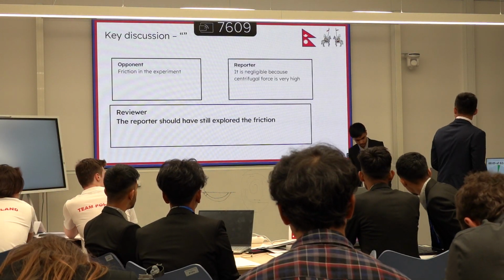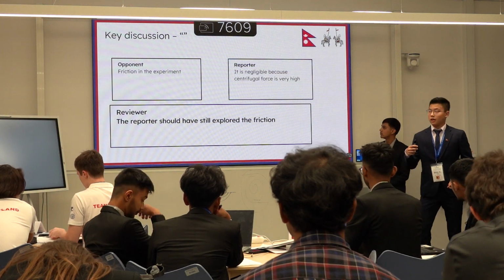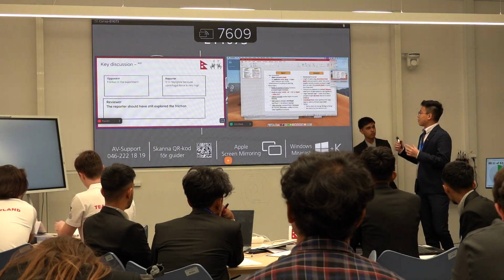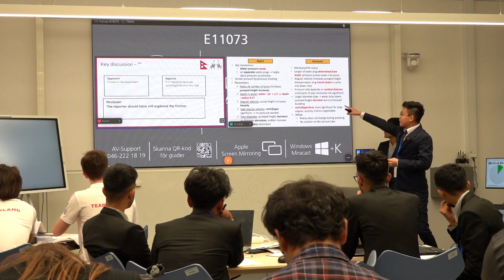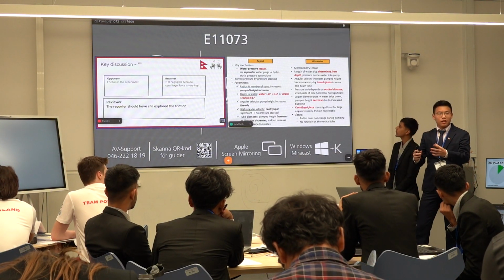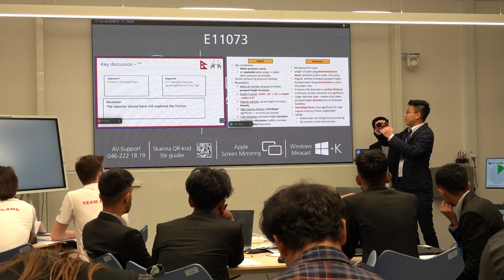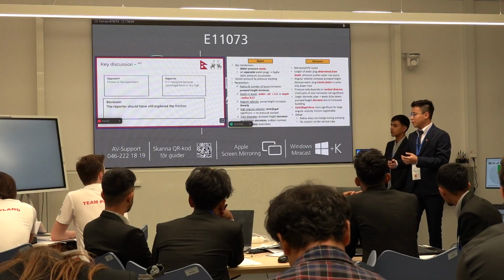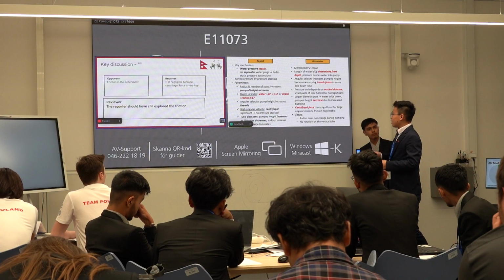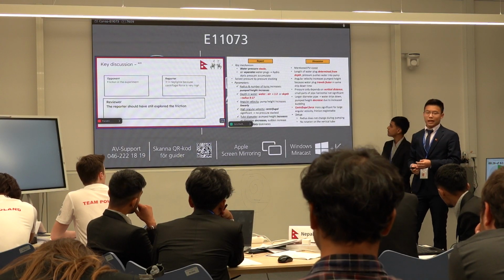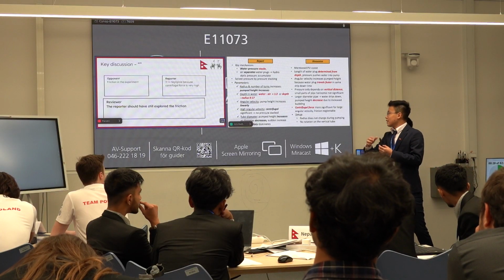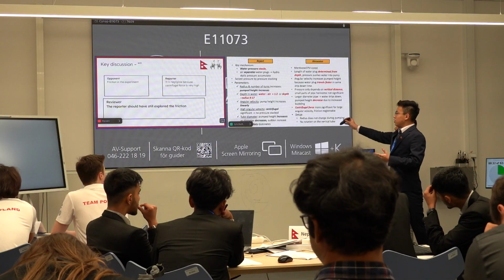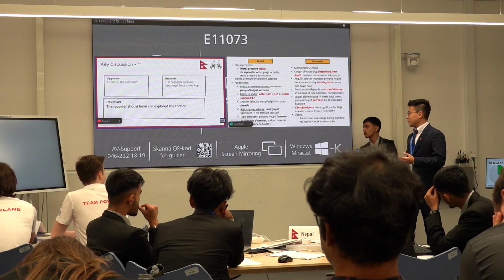Two minutes concluding remarks. So the main way the pump works is by hydrostatic pressure stacking, and the air separates the water plug and makes the airlock effect, making all the hydrostatic pressure stack up. And I also solved the pressure by the accumulation recursive theory. The parameters I've solved, first, are the radius and the number of turns. As we see, the pump height increases. Then for depth in the water, the optimal ratio of water to air is 1 to 2, or depth to radius ratio is 9 to 17.